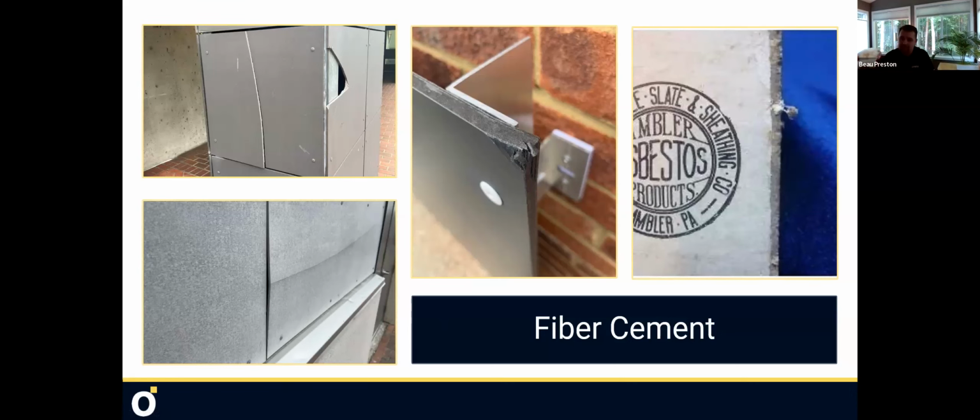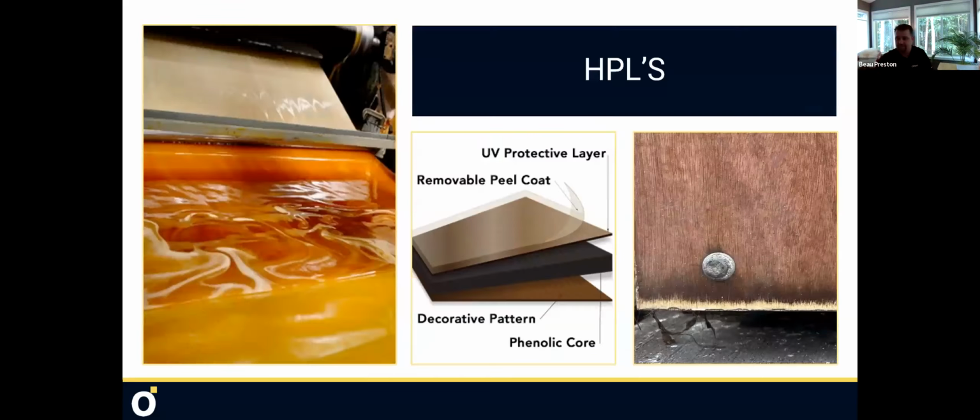Snapped right down the middle because it's too tight. You can see that it's overlapping, it's shiplapping on its own. That means they didn't drill the holes well enough and they're pressing against, and the whole panel is expanding thermally or hydrothermically, and it's breaking.